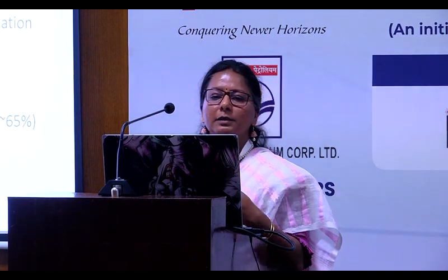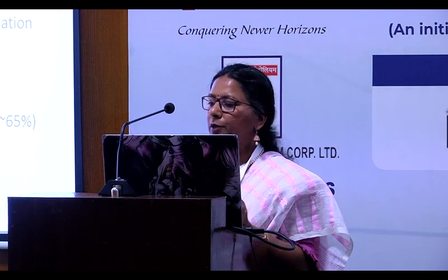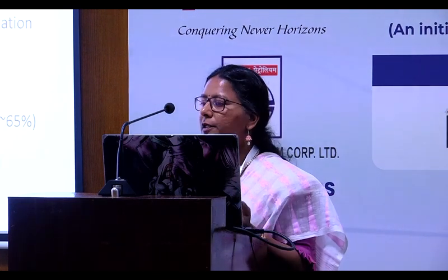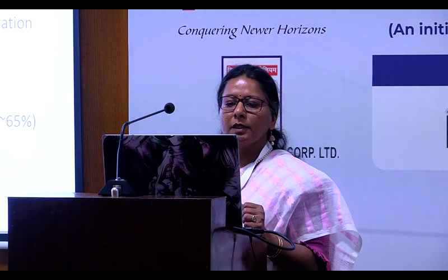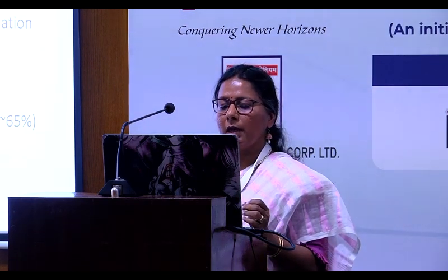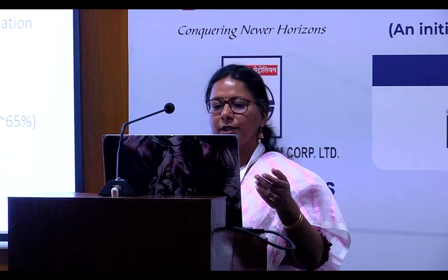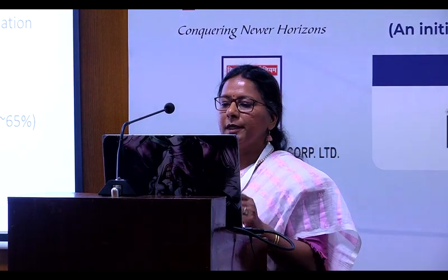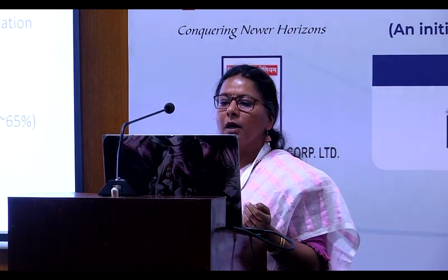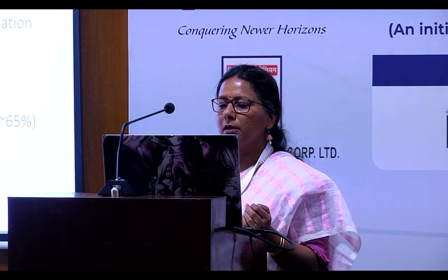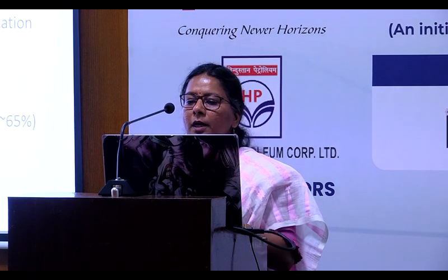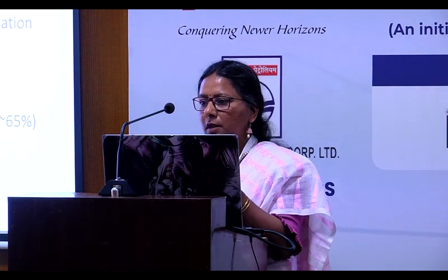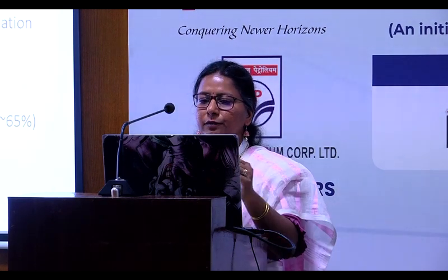How do we go about selection of the thermal insulating coating? We have to identify the prone areas, then identify the risk or criticality of the area, consider safety of course, and then based on the process. For class 3 hot insulation, metallic guards are the conventional option, but apart from that we can go ahead with the heat insulating coating, which can save almost 90% of the volume, and the space requirement will also be less when you apply these coatings.